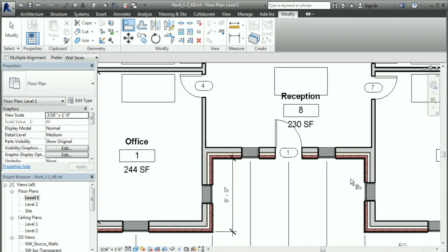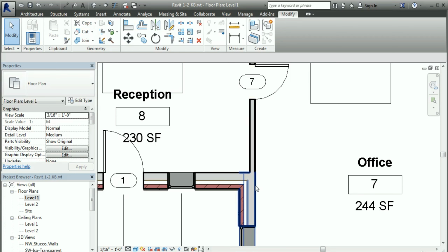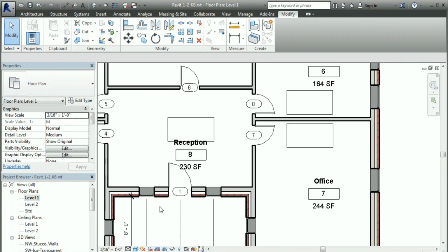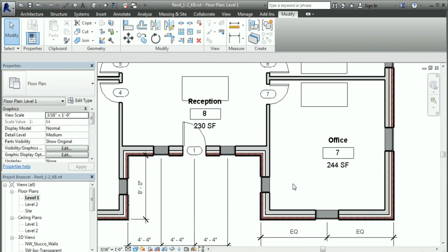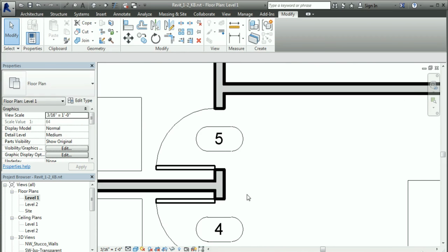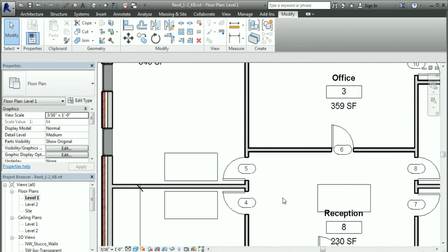Now, you don't have to move these off alignment. You can create the alignment even if they already are in alignment, just to create a lock between them. So I can choose lock this face, and then just pick that lock icon. And now, if the width of this inset bay changes and increases, these walls are going to move to adjust and follow that.